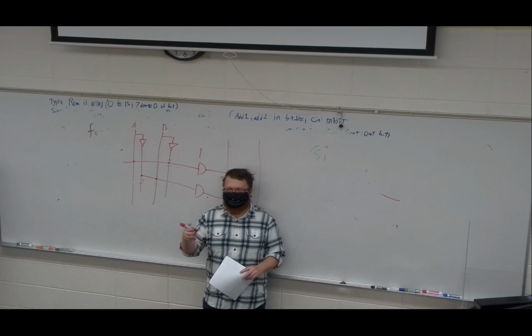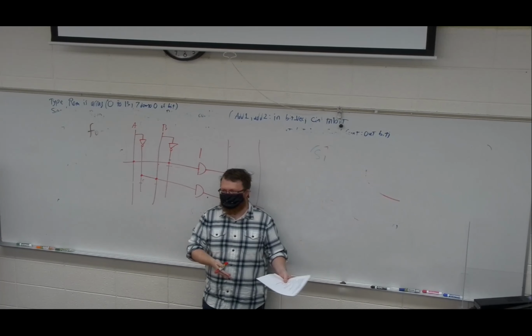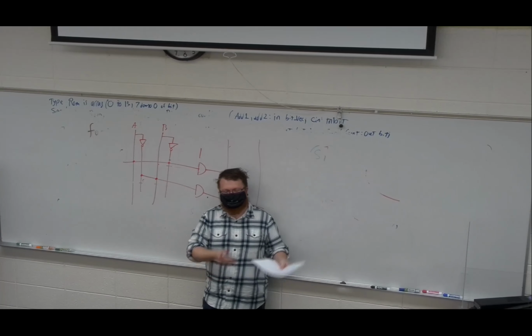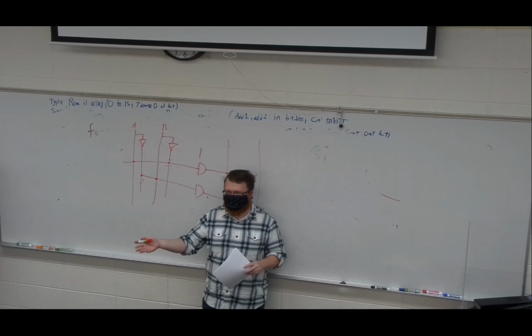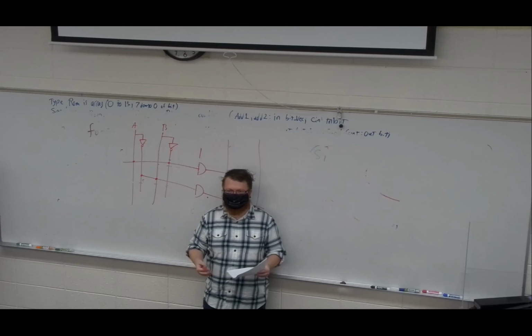I might also create an issue that doesn't look like it has any errors in it, but when you try and synthesize the design, it pops up with errors. So you're going to have to run synthesis and then use the Tcl messages window in the log to identify and fix whatever that problem is, right? So debugging issues in code.